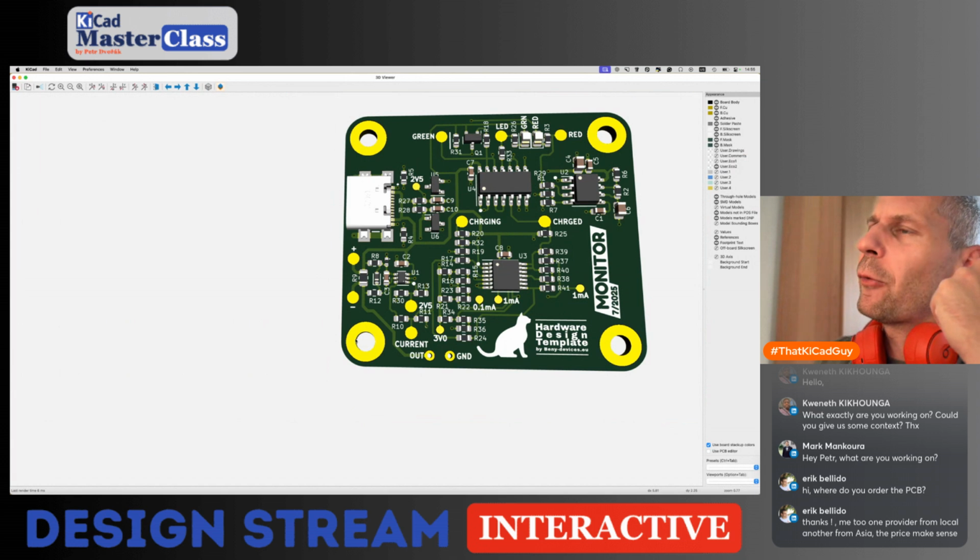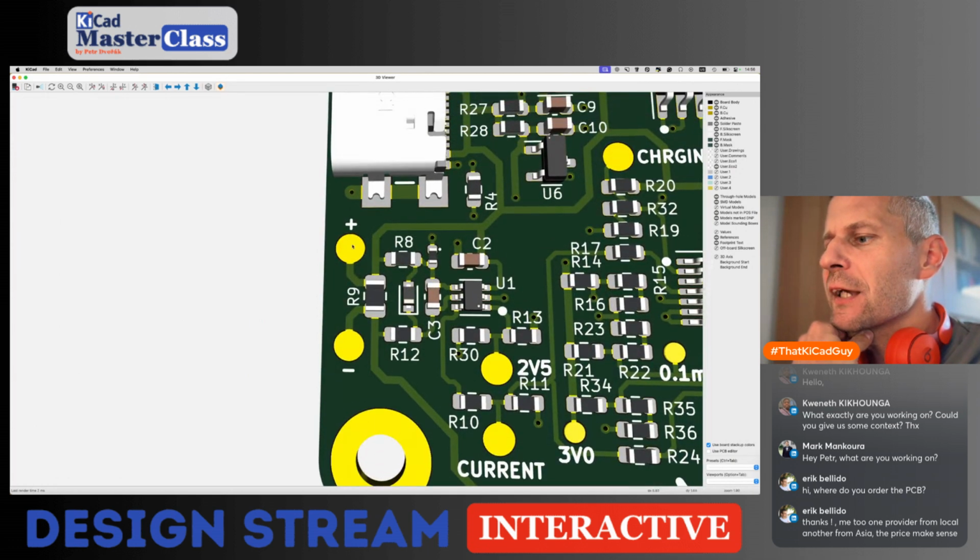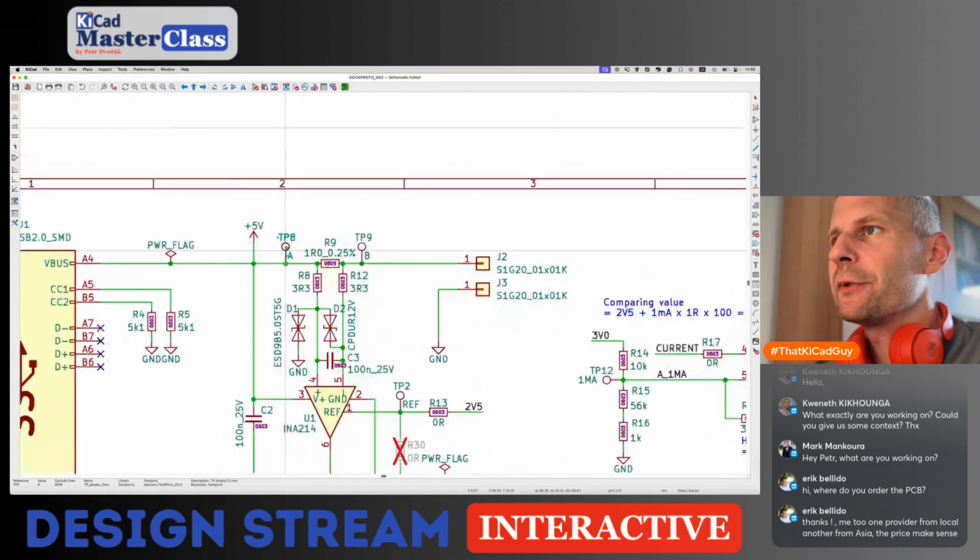Yeah. Now I remember. I placed the ground hook to the mounting hole because the mounting hole is grounded, and the other side was basically at the V bus, which is the plus, the A test point. Yes.